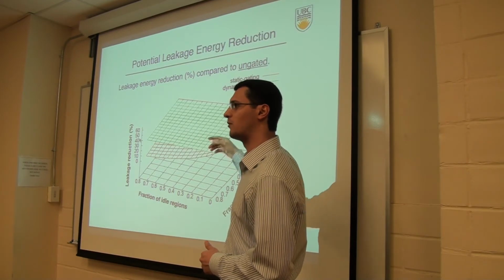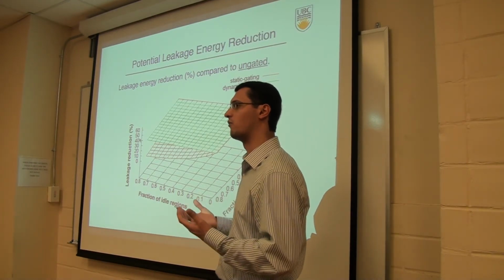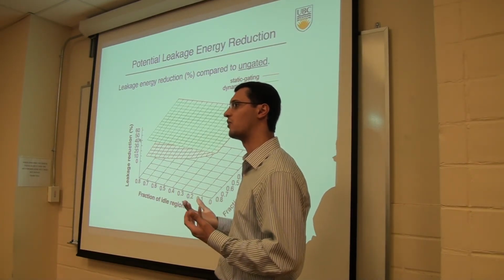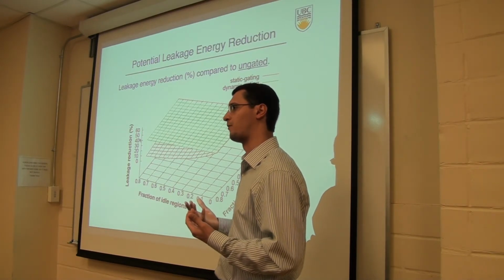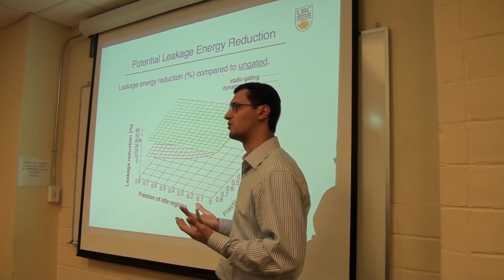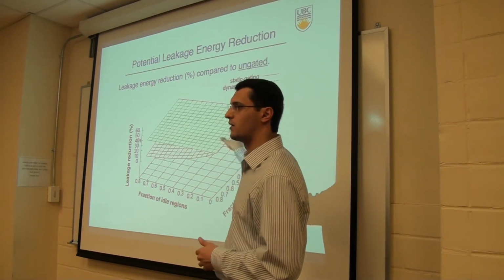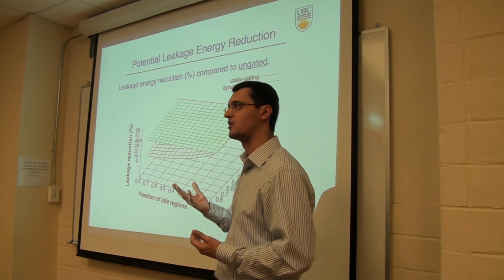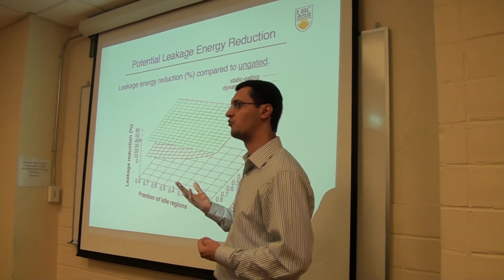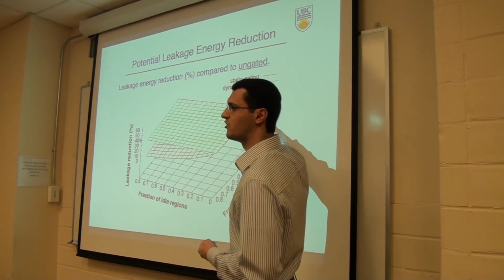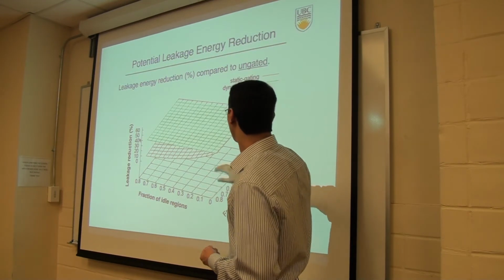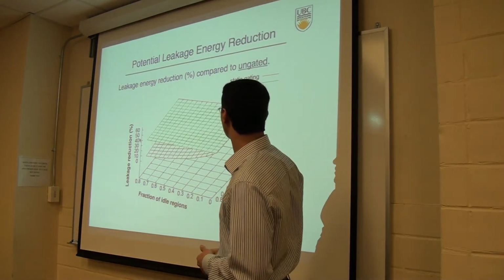This is because dynamic gating basically is equivalent to static gating in the sense that you can just turn off things that are unused, because everything will be used all the time. And because dynamic gating has some extra circuit components, it has more leakage power overhead, so the static gating achieves more leakage reduction.